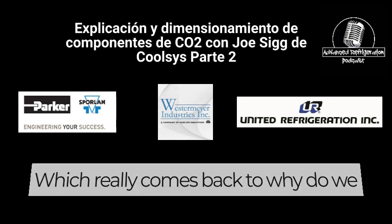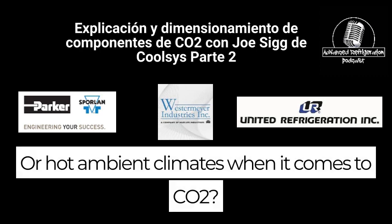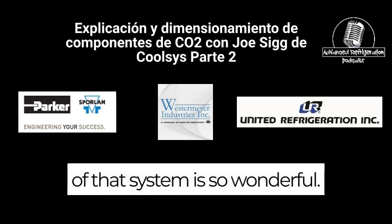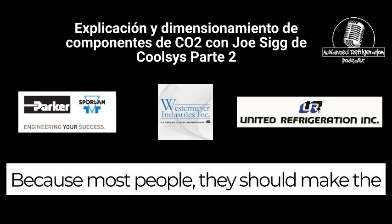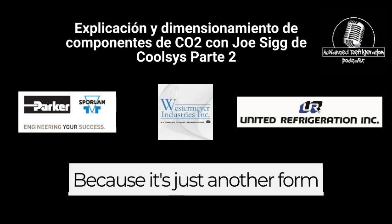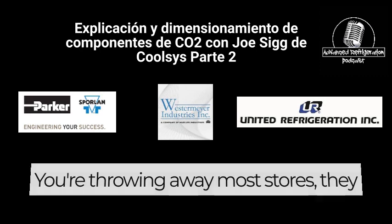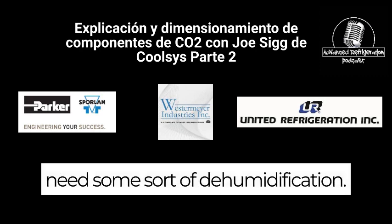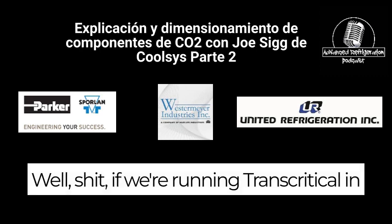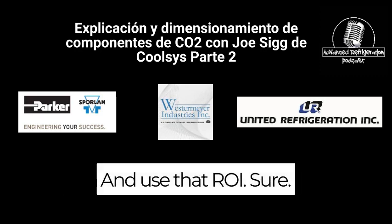Which really comes back to why we have to worry about hot ambient climates when it comes to CO2. It's because the heat generated off of that system is so wonderful. Most people, especially down south, should make the investment of actually utilizing heat reclaim because it's just another form of high ambient strategy. It's just another way to get rid of more heat that you're throwing away anyway. Most stores need some sort of dehumidification. When you have dehumidification, you need some sort of constant heat load. Well, if we're running transcritical in the middle of San Antonio, Texas, just roll it. You know what I mean? And use that ROI.